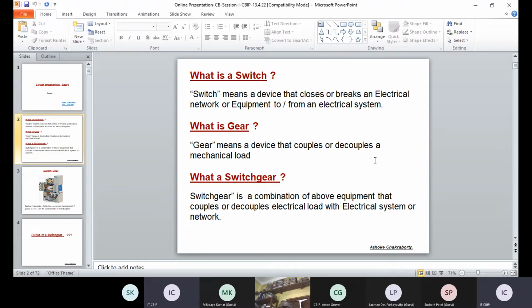And what is the purpose of the breaker? The purpose of the breaker is to switch on and off, not only the load but also the faulted condition. So who prompts the switchgear to isolate during a fault condition? Relay senses, sir. Correct. The relay is the intelligent device placed in the switchgear control panel. And who feeds the relay? Where does the relay get its signal from? The relay is connected to the CT secondary. Correct, CT and VT.